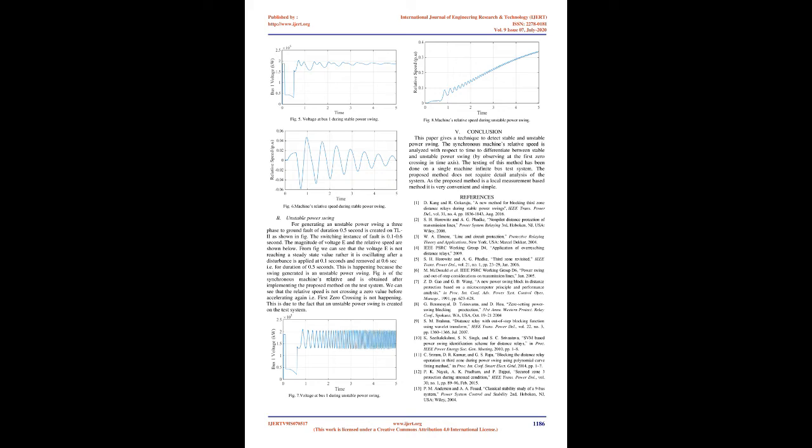3. Proposed first zero crossing scheme. Fig. 3. Single machine infinite bus system. Fig. 3 shows a SMIB system. The real power P, reactive power Q and voltage E∠δ are measured locally at the relay. Voltage V0 is the infinite bus voltage or slack bus voltage. In phase 1 of the proposed method we calculate the two unknown quantities, i.e. the equivalent system reactance/impedance Z and load angle δ. The power flow equations for the SMIB system are given as follows.